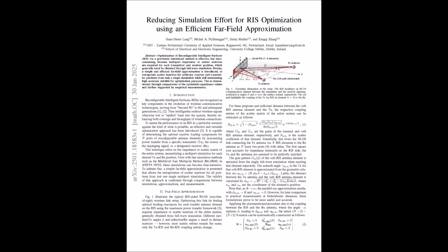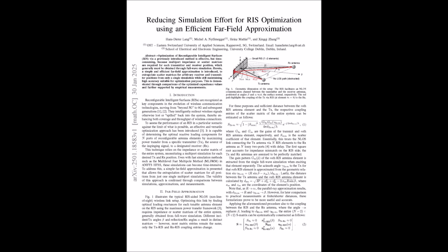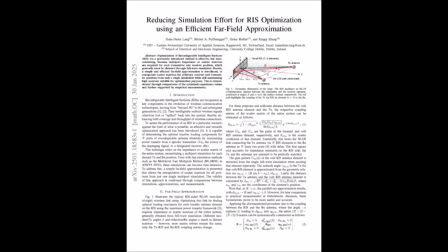Okay, so first, they fabricated a small-scale RIS. It was the same size as the one they simulated, just 7 rows by 2 columns, operating at that same 3.55 gigahertz frequency. And get this, they incorporated varactor diodes into each of the elements. Now, remind me, what are varactor diodes again? They're essentially tiny electronically controlled capacitors. Think of them like little knobs that allow you to fine-tune the capacitance of each element on the RIS, giving you real-time control over its response.